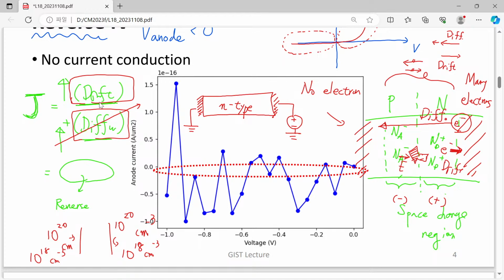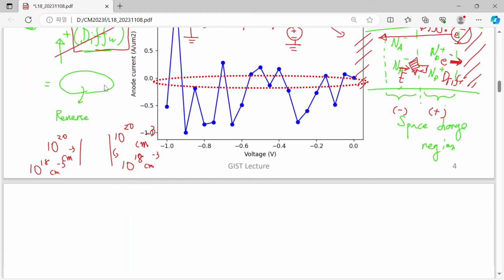So now it becomes much easier to match this balance between drift and diffusion, and your numerical problem can become much easier to solve. Simply speaking, if you have a high internal electric field inside your device, then it becomes difficult to get the leakage current accurately. That is a common tendency you can observe. Okay, are you okay with me?